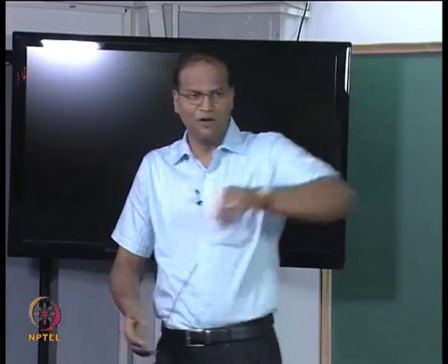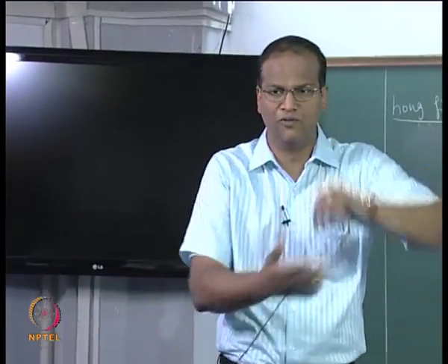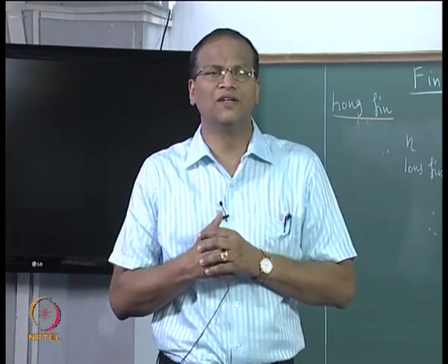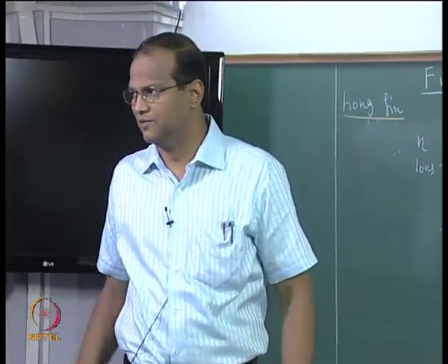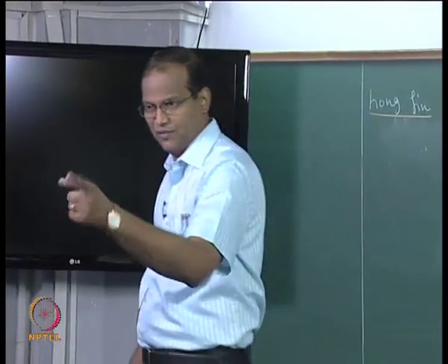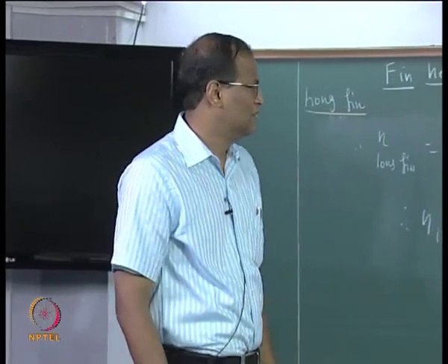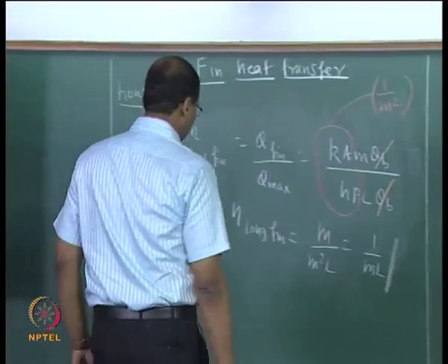Instead you can cut them down and crowd the base with more fins. Of course that may locally affect the heat transfer coefficient, but you can put some fan, increase the velocity and do something. That is what I showed you, the heat sink with a fan and very closely packed fins, alright. Now how long is long? That question has to be answered.